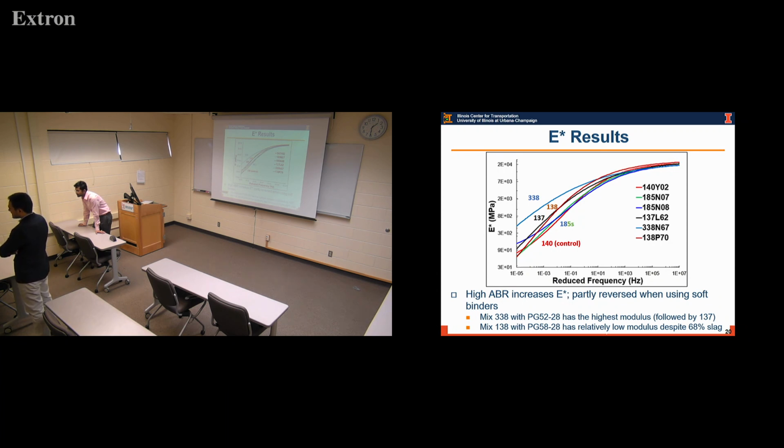Even more than that, the problem with that opening is that it's typically rounded. And in DIC, you need to have a flat surface. The algorithm assumes that you have a flat surface. If at least one surface is flat, you can at least compare along the length, with the small area that we have, where it initiated. It's very limited. But my main concern is what the professor says: it's rounded, and DIC will not work for our application. You will need something like 3D DIC to evaluate that.